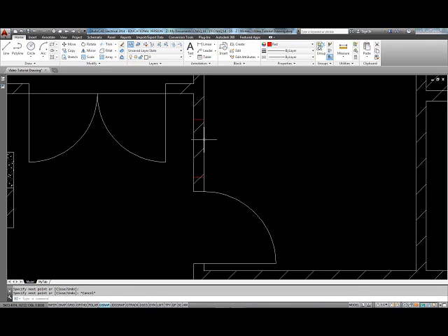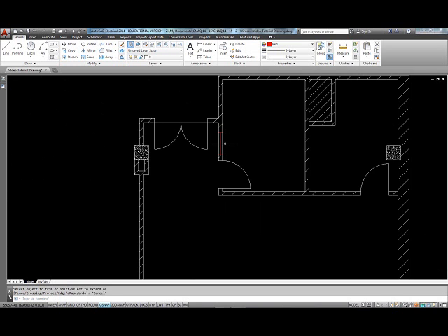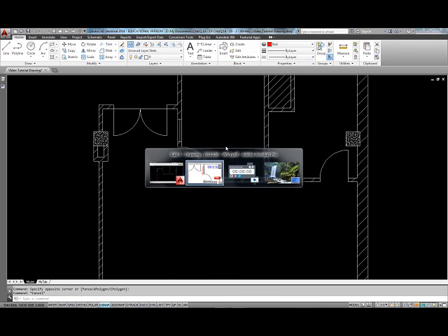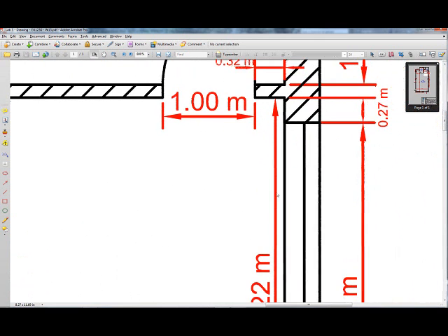Now let's choose this one, this red color, move from this end to the middle, and then let's trim from this point, or these are the two cutting edges, space bar, and then trim this hatch pattern. So click on one of the lines and that does it. Now we can choose these and go by layer, and that's our first window. And let's go to the other windows here on the side.